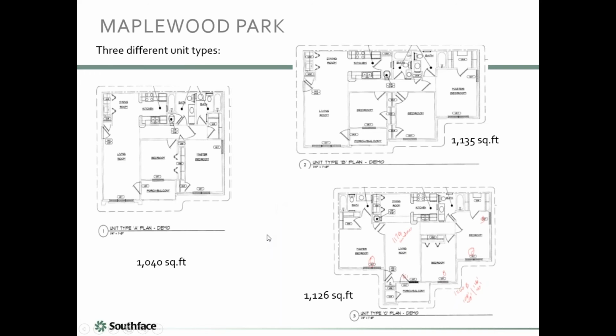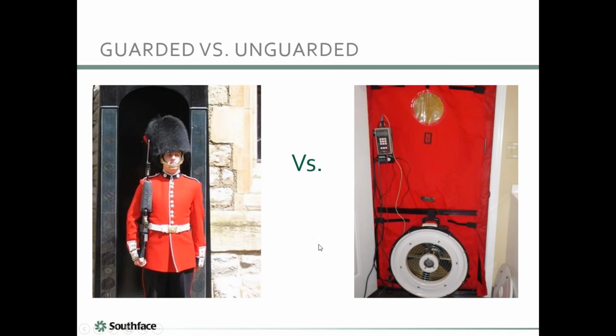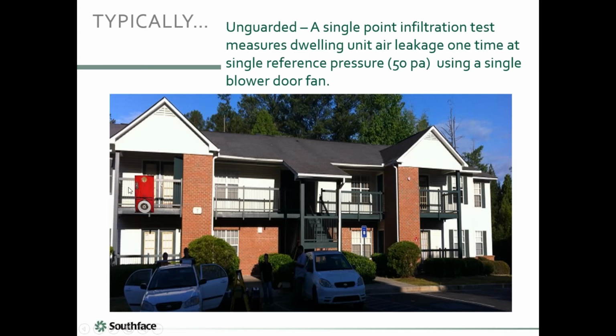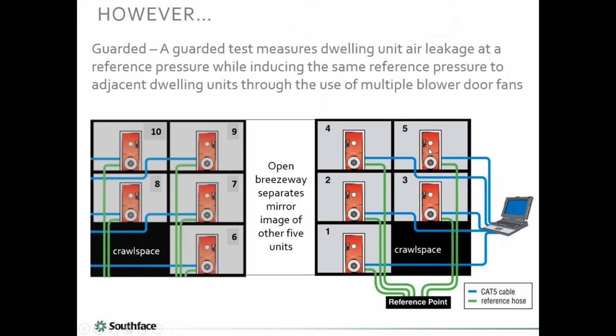And all I had to go on was where the leaks are. Sometimes they're across the common walls, and it was hard to ascertain a whole lot more than that. These, I believe, were just one story, with no conditioned floors above, so it was like a row of apartments, and you would test the middle one, for example. We tested unguarded, then we tested guarded, and the difference in the reduction number would tell you how relatively leaky they were.